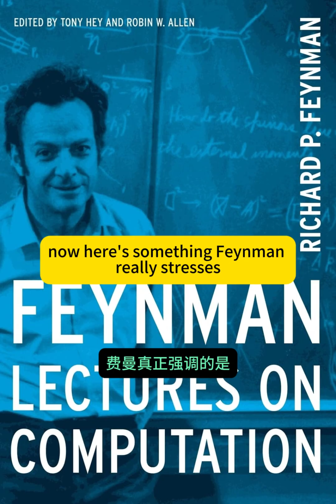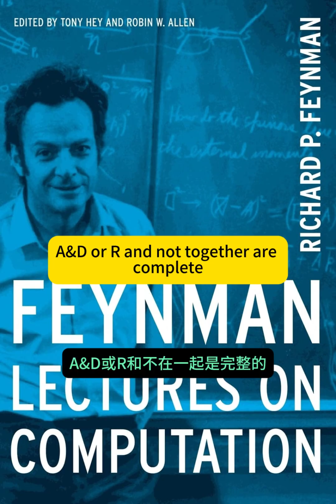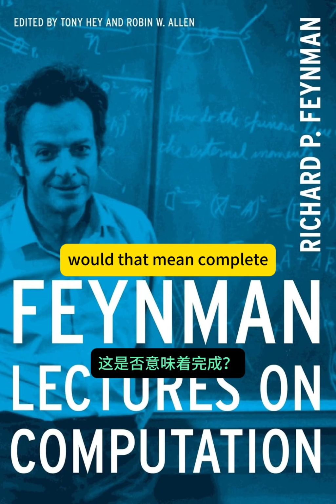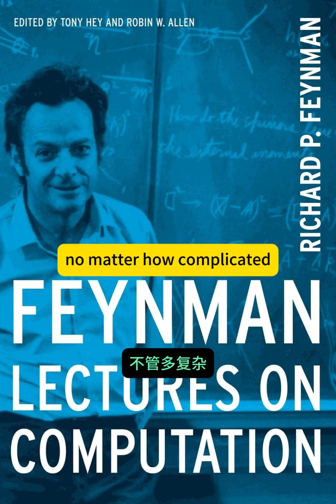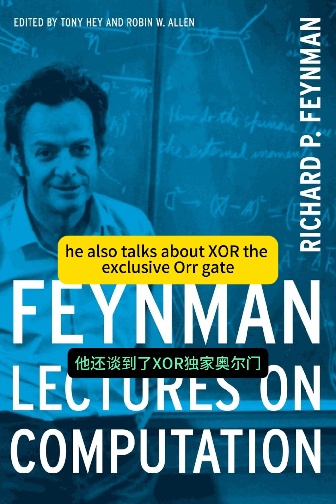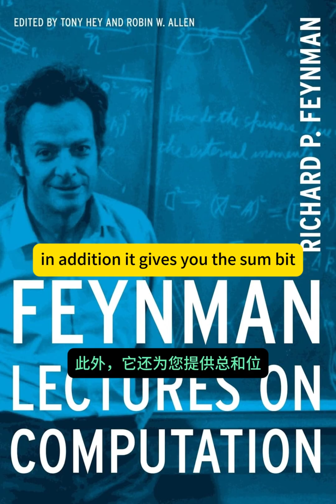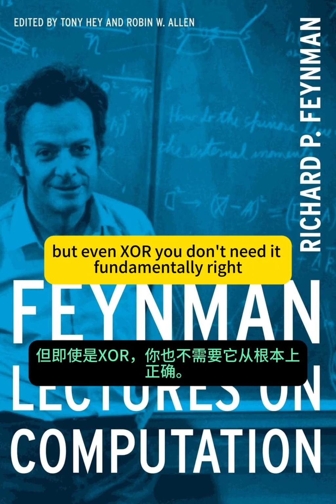Simple inversion. Now, here's something Feynman really stresses, and it's a powerful physical idea. AND, OR, and NOT together are complete. What does that mean, complete? It means you can physically construct any possible logic function, no matter how complicated, just by wiring together combinations of those three basic gates. That's it. It's pretty amazing. He also talks about XOR, the exclusive OR gate. That's useful. In addition, it gives you the sum bit, while an AND gate gives you the carry bit we mentioned. But even XOR, you don't need it fundamentally, right? Correct.